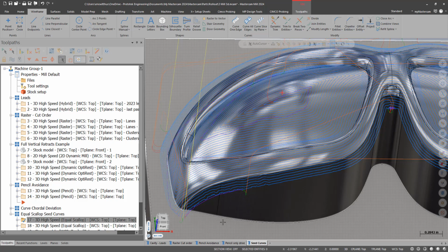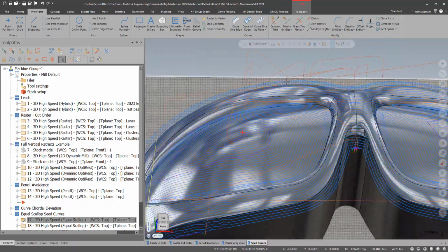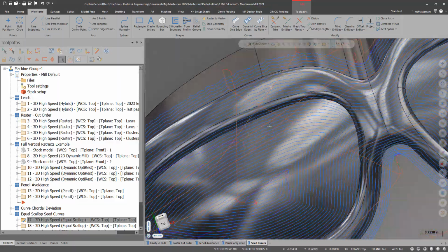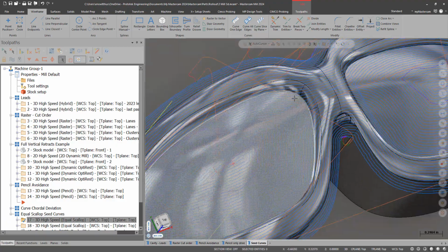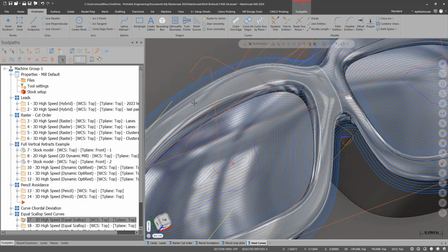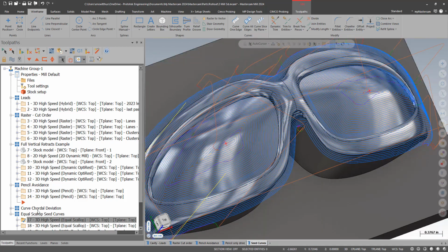I have a tolerance there. It can also be caused by drive and check faces, and then I adjust that with stock to leave on my check. That's just a traditional scallop. The scallop is a great toolpath because it leaves an even finish everywhere. But the downside to it is it's all patterned off the outside shape. And sometimes I have internal corners, and then my toolpath shape doesn't match the internal corners, and it doesn't look great. I could finish that up with a pencil. That helps a lot. But I have some other options here as well.